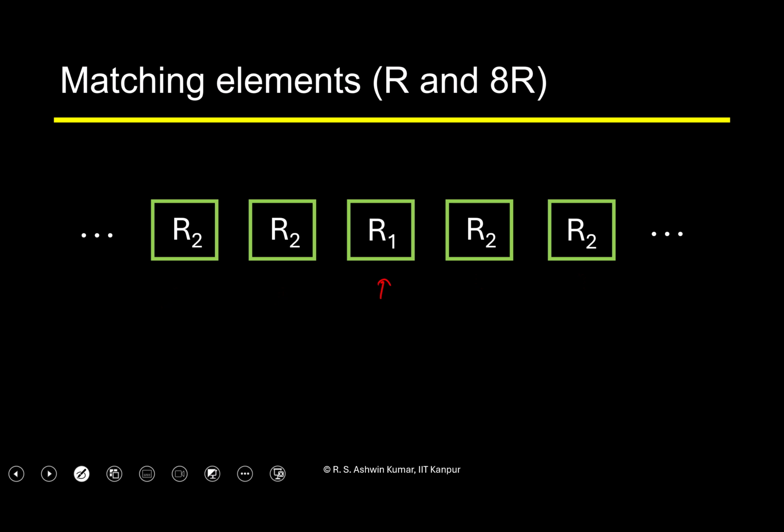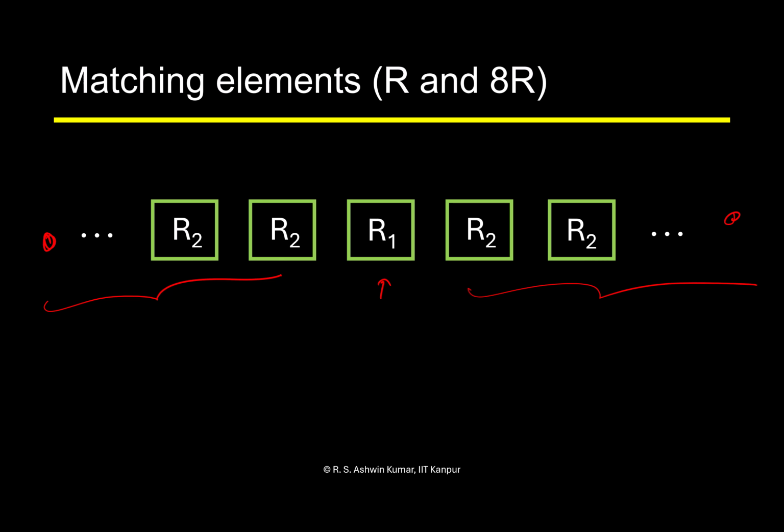So again, this will be R. Here you have 4 times, here you have 4 times, and you put them in series. But if you do this, you see that the spacing between the resistor at this end and this end is going to be really large. It turns out the relative mismatch, in addition to being inversely proportional to the square root of area, is also dependent on the physical spacing between the elements. So instead of spacing them in a long 1D array like this, to make the spacing short, what can we do?